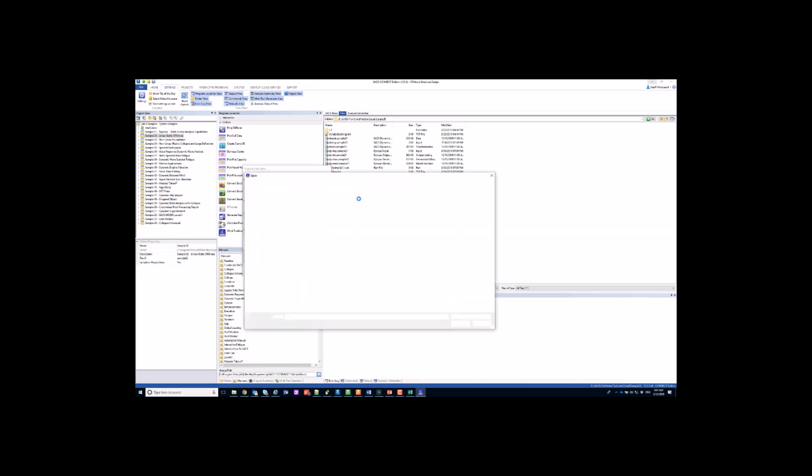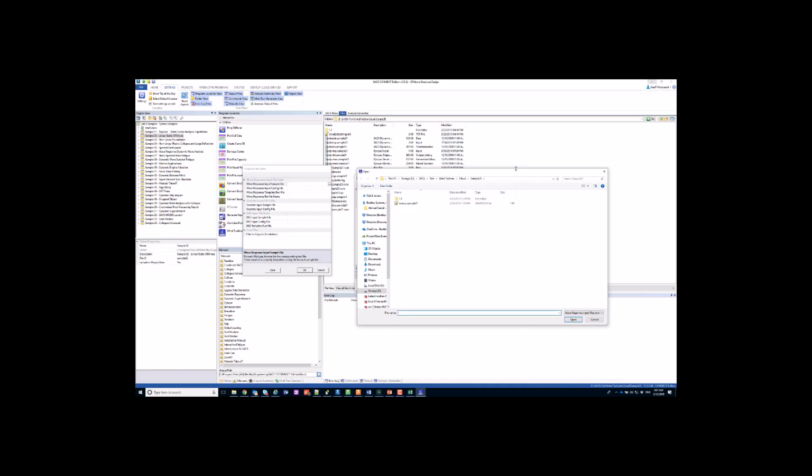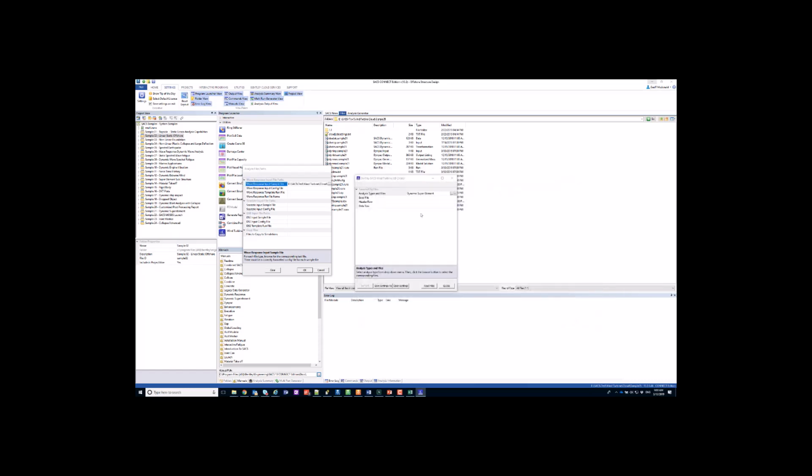So if you're not familiar with the Dynamic Superelement, essentially what we do for the Dynamic Superelement is we have a wave response input file, and we have a Dynamic Superelement input file. We run that analysis with those inputs, and we're going to generate a Dynamic Superelement to be used with other wind turbine analysis programs. But it's going to essentially work the same way for strength or fatigue analysis. You're going to be selecting your wave response input files and just all the input that you would need for that analysis. You're just going to have these partial input files.